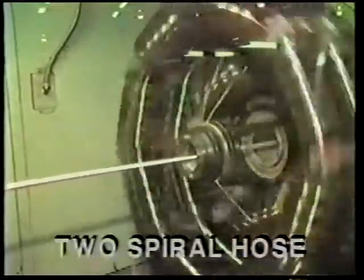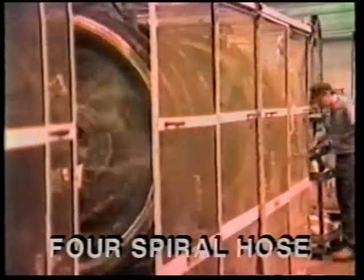Spiral reinforcement is another popular method of applying the reinforcement. 2 layers of textile yarns are applied over the tube. One layer is spiraled in a clockwise direction and the other in a counterclockwise direction. This is referred to as 2-spiral hose. Another double spiral may be added to obtain higher working pressure, resulting in a 4-spiral hose. The advantages of spiral reinforcement are excellent flexibility and lower manufacturing cost. This construction is popular for many air and water hoses.